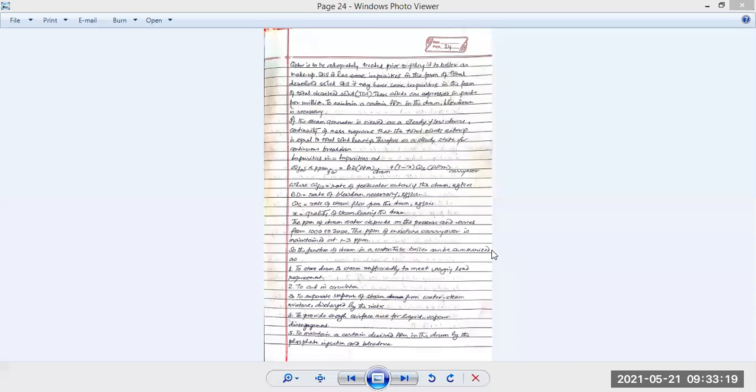So what we are going on here is that we have to clean the water before going to the superheater by certain artificial means, and that will not be costly and is quick, but you cannot allow the deposited salt inside the superheater itself. There's a specific amount we can allow, which is much less, almost nothing. There should not be any deposit at all.